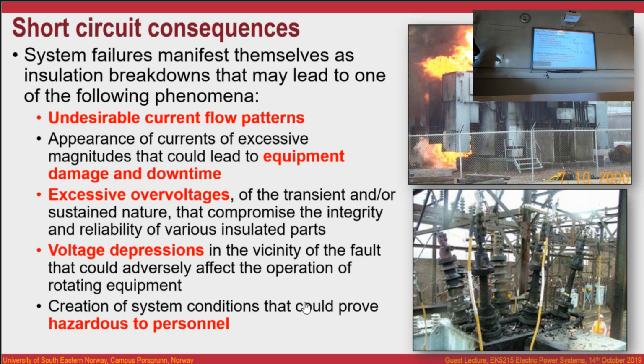When you are making short circuit calculations, you must assess all of them. 3-phase, 2-phase to ground, double phase, single phase, okay? What is the idea? You must know which one of them is the worst. The worst case scenario must be prevented, okay? I am tired, and I don't have coffee here.